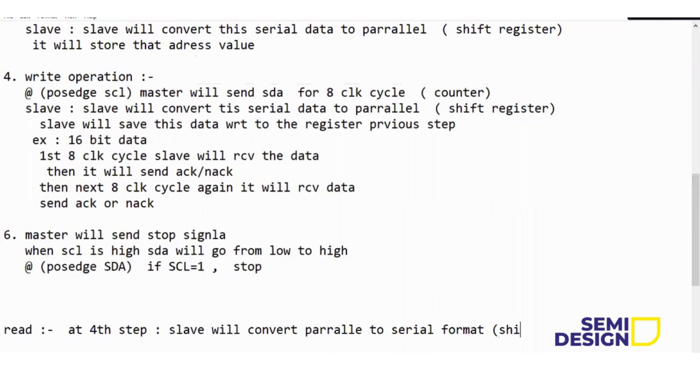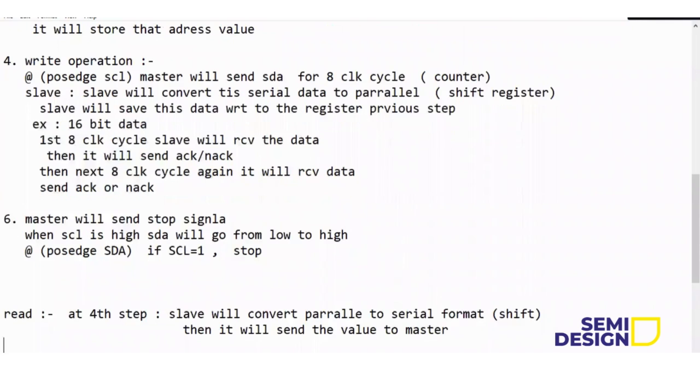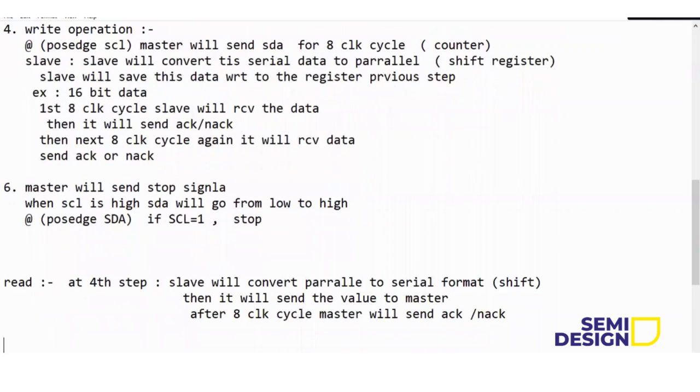This also requires one shift register, for the parallel to serial format. Then it will send the value to the master. And after 8 clock cycles, the master will send the ACK or NACK. Okay, now this part is completed.